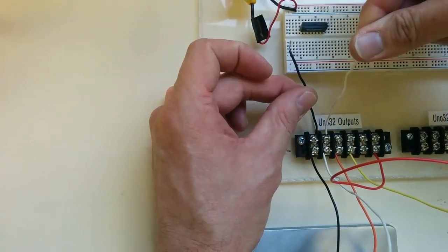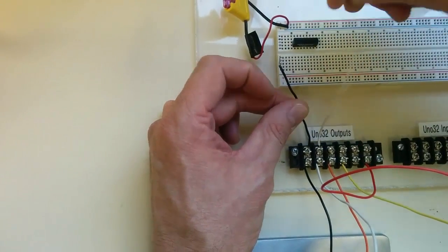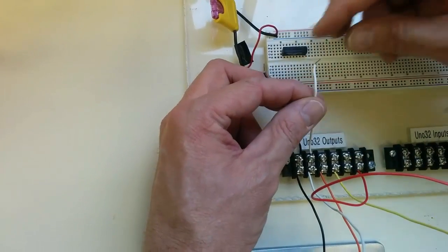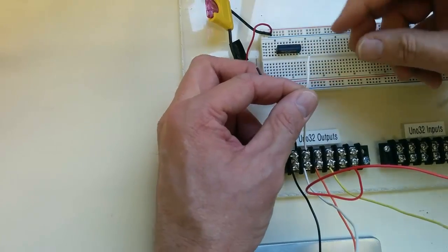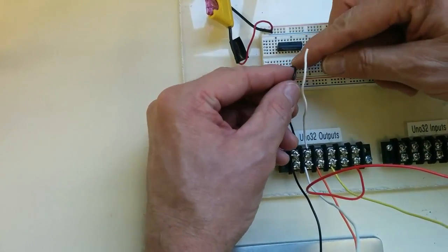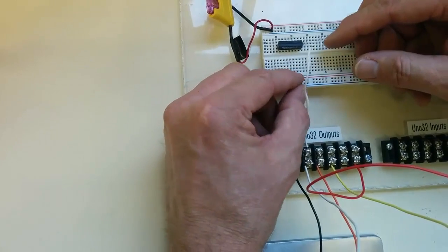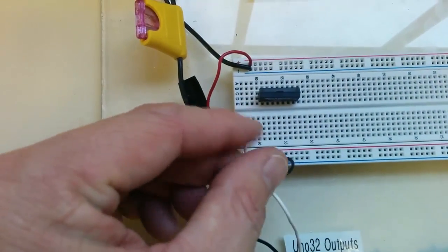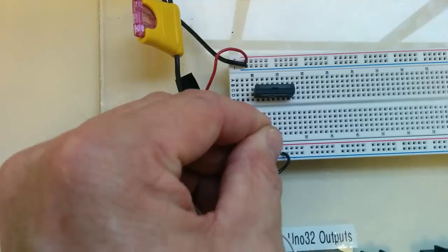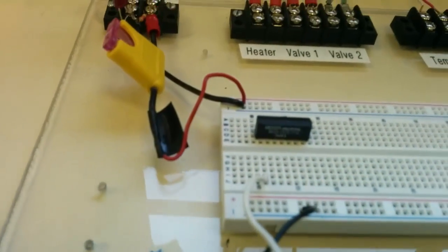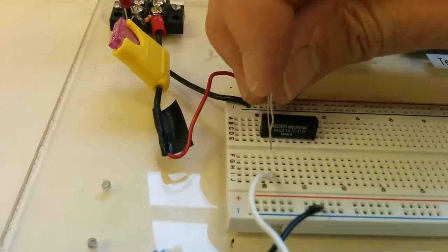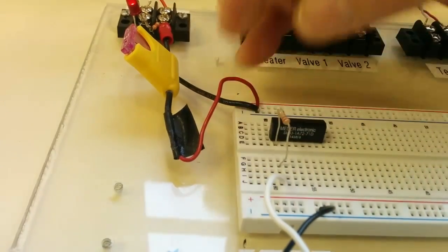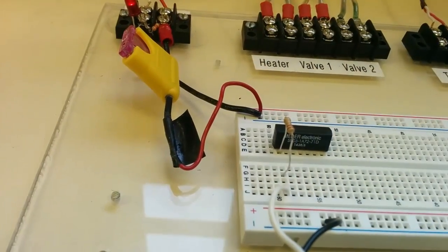So we've got 3.3 volts coming from a digital output. We're not using red because it is a control signal. And so the ground is going to come in and get placed in the lower section of the edge, and the 3.3 volts or digital input is going to go into one of the lower sections. Now, I selected a resistor to demonstrate the circuit wiring. You're going to have to decide what resistor to use. I'm going to come from the same digital input into pin 1 of the relay.